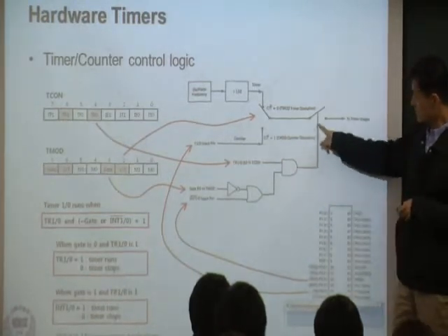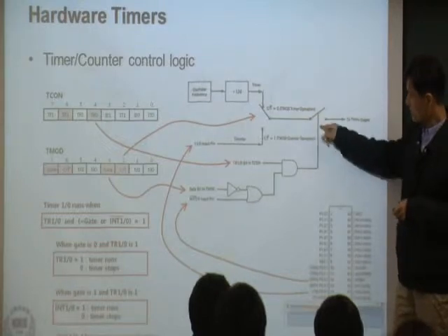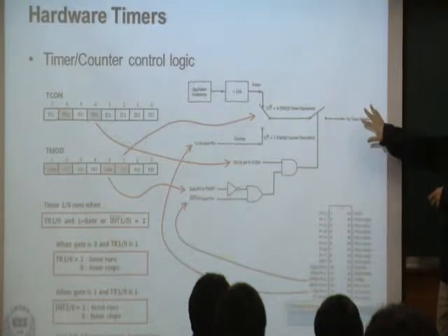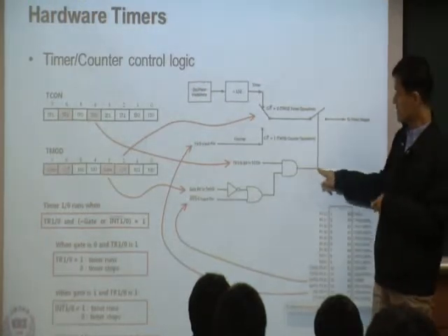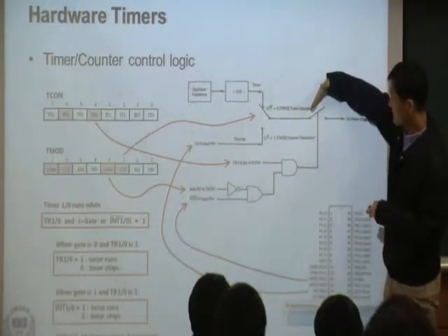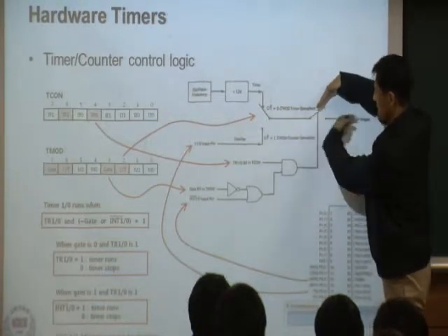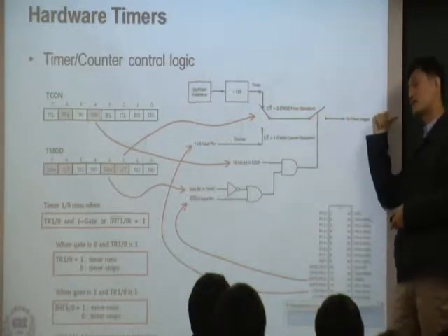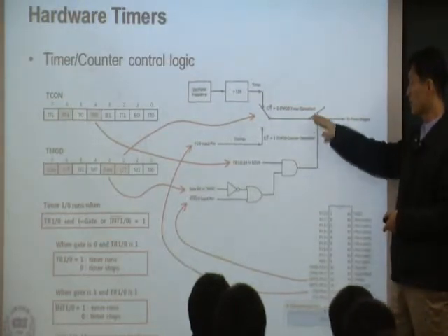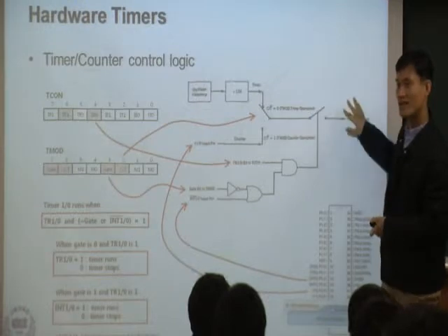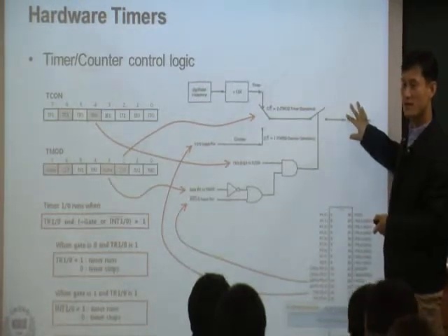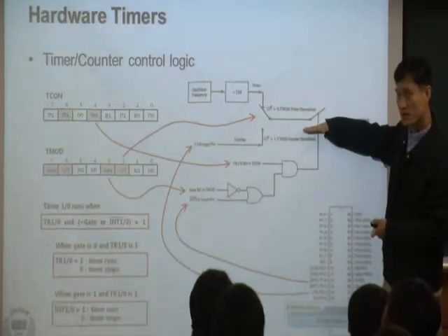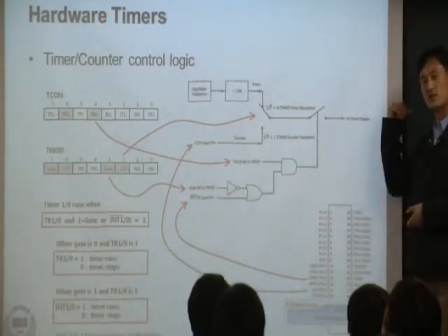In this case, what is this switch? This is the switch to connect. This is the first stage. This is the next stage, the timer stage. So if this is a 0, that means disconnected. So no pulse is going there. We have a pulse coming in, so that pulse has to go to the next stage. But if you have a 0, then it's disconnected, so you get nothing. You don't have any pulse. So this has to be 1. That means the switch is closed. So now the pulse is going there to the next stage.